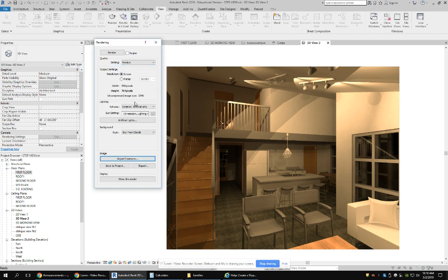The last piece you can do once you've decided the kind of rendering you want is then take the time to render a best image, and the quality of the image should improve. You won't see such sharp lines here for the edges of the lights, and you'll get hopefully a better result. But don't waste your time with best until you've fiddled around with medium and gotten something that you think is halfway decent. The best time can take probably upwards of 20 minutes if you've got a lot of lights and a lot of algorithms for the software to have to calculate through.